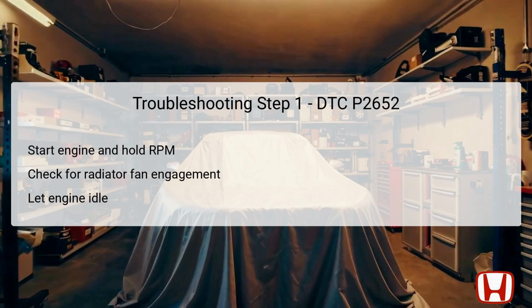After sustaining the RPM, it's crucial to monitor when the radiator fan engages, as it signifies that the engine has reached sufficient temperature. Then, allow the engine to idle. This process is essential as it helps establish a baseline condition for the oil pressure readings that will be taken later on, providing a context for diagnosing any abnormalities.